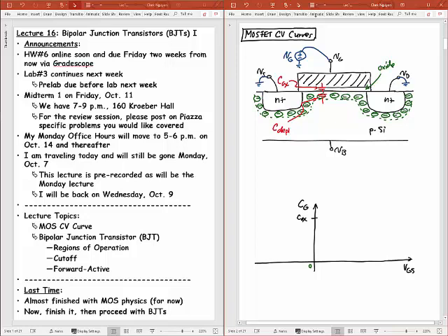And as you know, as I increase this gate voltage, this depletion capacitance will keep increasing in size here. In other words, the depletion region will keep increasing in size until I get some maximum depletion region size, at which point inversion starts happening in this channel. And so I can plot on this sort of the capacitance associated with my maximum depletion region size. And when I do that, I have a series of capacitors like that.